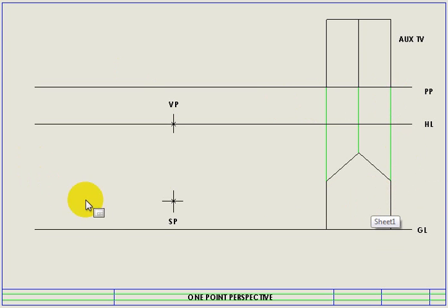Alright, typically there will be another one of these drawings over here, and it would be a replica of this one on this side, so that I could simply project that height across over there for the tip of the roof, and the height across for where the actual building stops. Okay, I'm going to also just show that this point over here is a vertical line in construction.